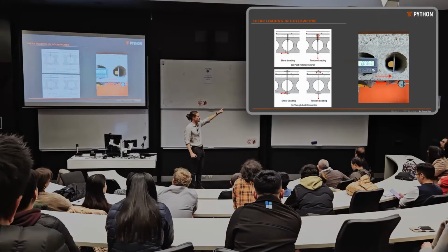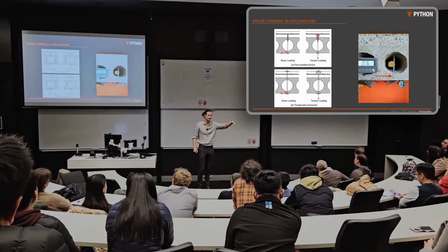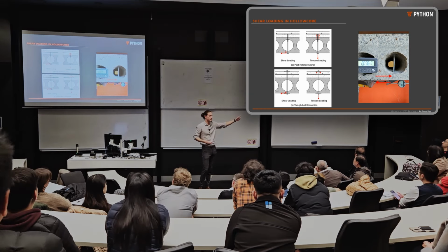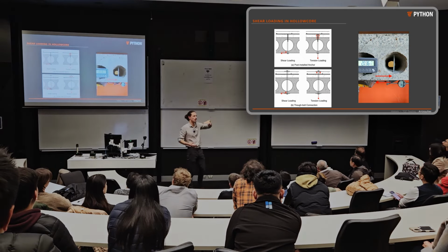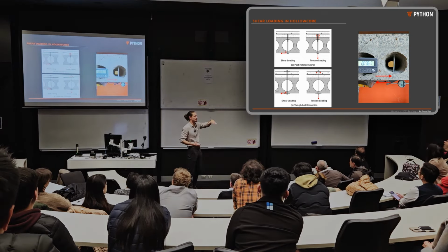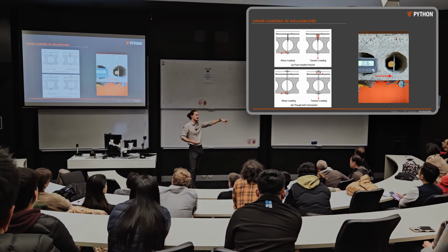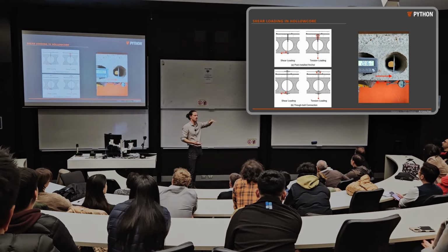In tension, the screw anchor behaves much like a post-installed anchor, right? That load transfer is happening through the threads. The through bolt, in comparison, is really a bearing connection on the top of the hollow core unit. Fundamentally more reliable, does not get designed using a C2 capacity, right? That's just first principles, steel and bearing.